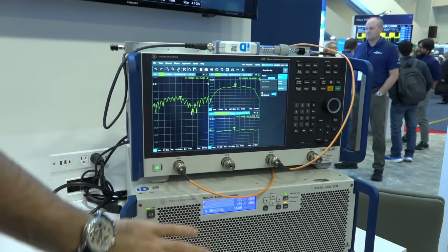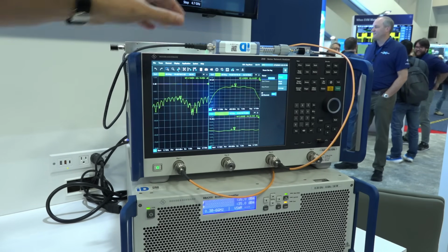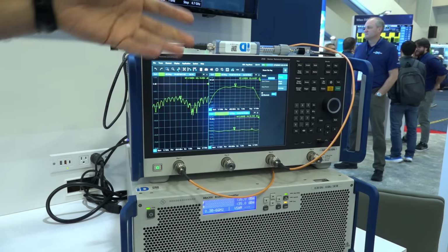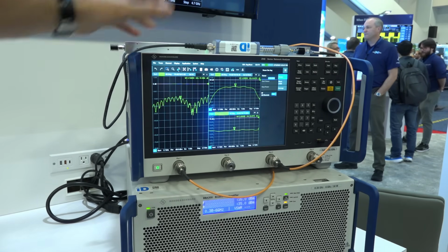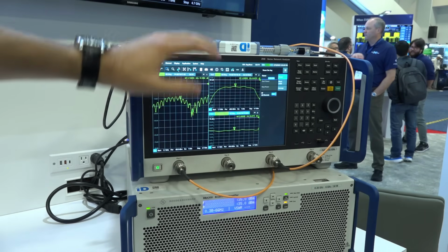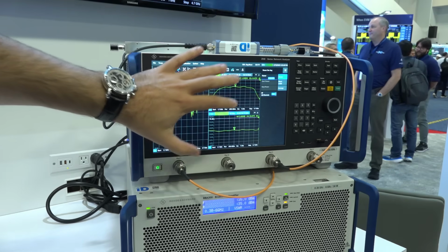And using the ZNB and the filter combination, you'll eventually build a characterization matrix that tells you exactly how that filter operates under these stress conditions, both in lab and production environments. Now there are couplers at the top, of course, because you don't want to put that huge amount of power into the instrument. And there's also a power sensor over here using a coupler, and all of the network analyzers